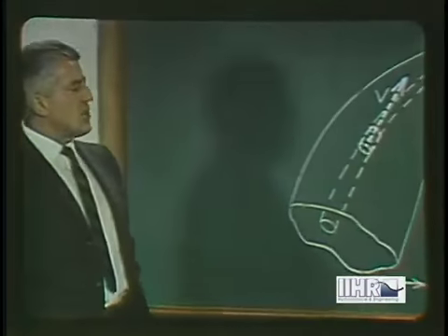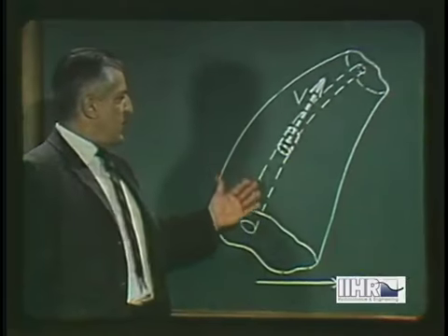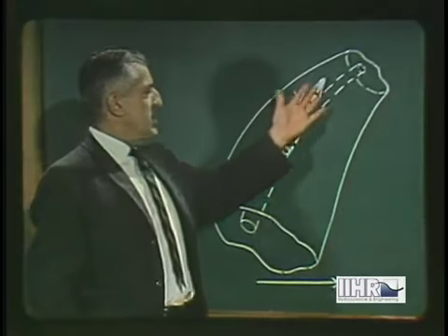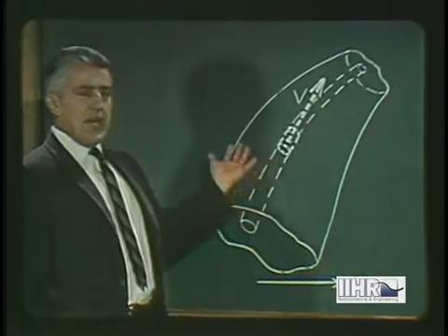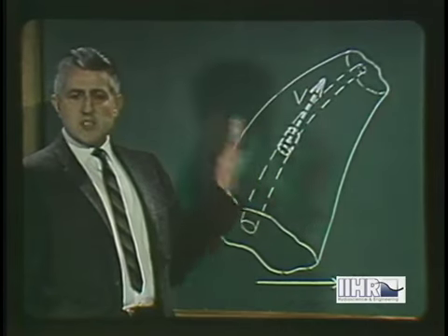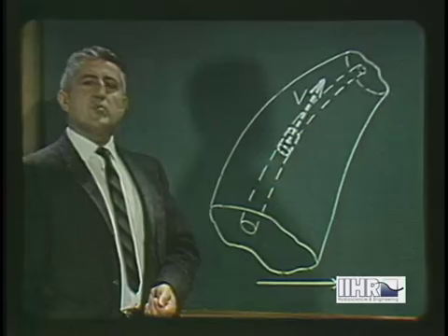The simple continuity and pressure-velocity relationships have permitted the comparison of conditions between various points of a moving fluid. Equally simple relationships are obtained by integrating the basic equations of motion not only from section to section along the same stream tube, but also from one stream tube to the next, so as to encompass a considerable portion of the space through which the fluid moves.